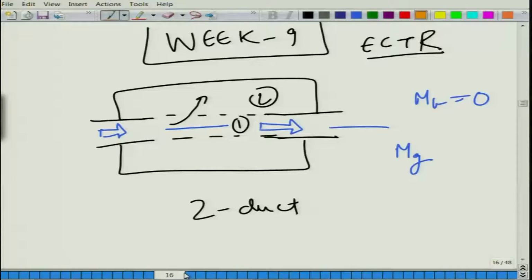So, for example, let us go back to our original configuration, let us say this one. It does not matter whether it is 2 or 3 ducts. The point is that they used to divide the ducts into small regions and get transfer matrices across this one and this one, and then their approach could account for the exact number of holes in each of the regions. So, they could account for non-uniform porosity also. It is like a discretized system.